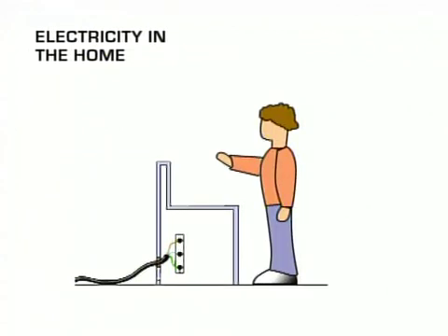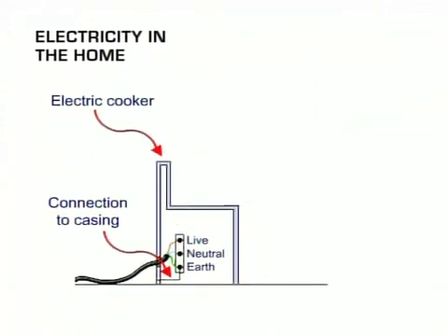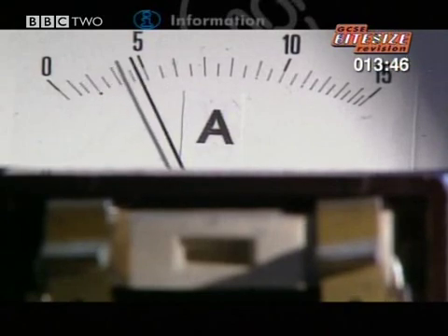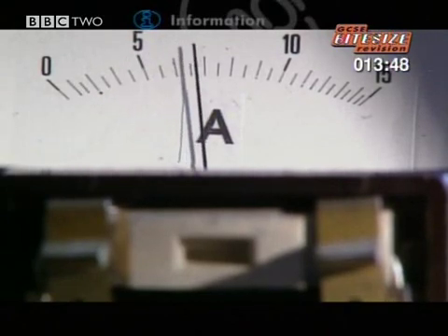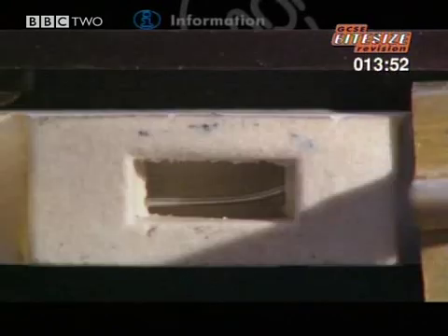If there's a fault in an appliance and the metal body touches a live wire somewhere inside, a person touching it could be killed. The earth wire allows electricity to flow to earth through the earth wire, blowing the fuse and not going through the person. A fuse is designed to allow several amps to flow before it melts. Its purpose is to prevent fires. It won't prevent electrocution.